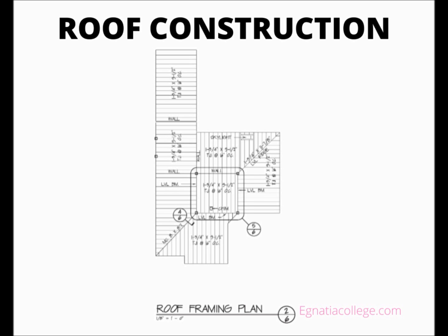The roof frame may also include collar ties. Collar ties are usually made of 1 inch, nominal thickness, lumber. They are normally included on every second or third pair of rafters. This information should be shown on the roof section if collar ties are planned. The slope of the roof may be shown on any section view that shows the rafter size. Slope is usually also shown on the building elevations.